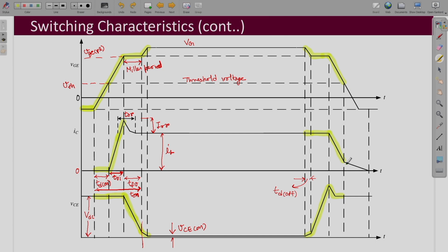Now, in the case of MOSFET we had seen that the current almost becomes close to the leakage current, but in the case of IGBT this does not happen. There is some significant current left over, which further goes to the leakage current, while the gate to emitter voltage goes from the threshold voltage to the actual negative blocking voltage that we apply in the blocking state.